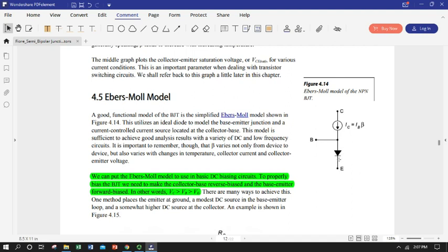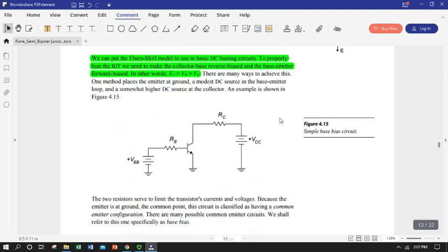And the forward bias voltage of that diode is going to depend on the exact nature of the semiconductor, but generally speaking it'll be 0.7 for silicon. Okay, now we are going to put that to work in a real simple amplifier circuit. So we're looking at current gain, so we're going to amplify the current that we can flow through the circuit. We're going to put a little current signal into the base of our transistor, and we're going to look at the effect that has on the current being supplied by our collector supply and flowing through the collector